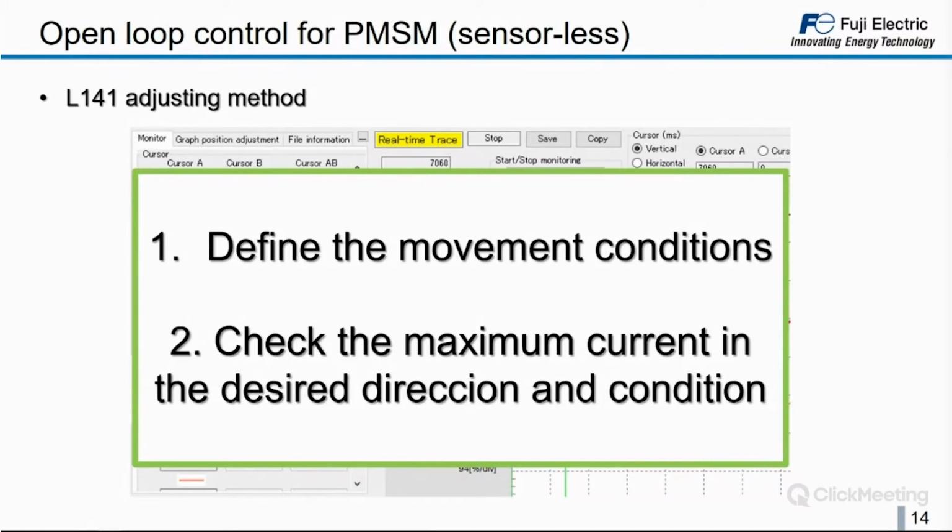The default setting is 80%. Basically, this is a good setting, it is correct in case of performing rescue of people in the braking direction, or in case of moving the lift during maintenance when the lift system is not finished, so when the counterweight is not loaded, when the car maybe is not finished.